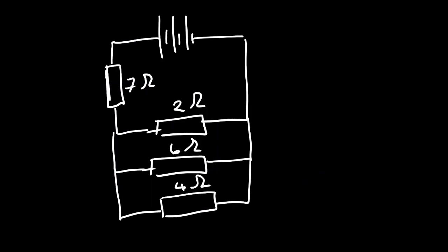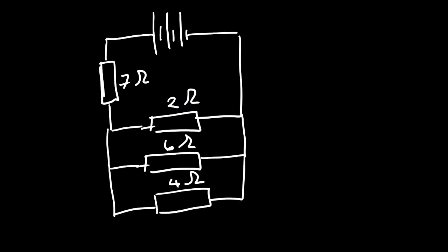Let us look at this example. Now this one is a bit different. We have the combination of 2 connections on one circuit. So looking at the direction of the current, it will move this direction, goes through this 7 ohms resistor. You can see that before the 7 ohm resistor, there is no junction or branch. So we can confirm that this is series connection.